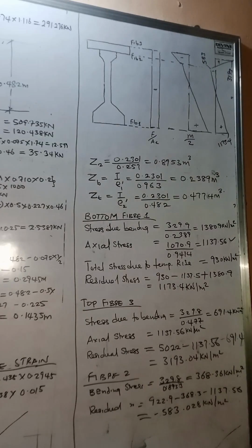All right, so this brings us to the end of this lecture. We can work out the reverse temperature for this problem to obtain the residual stress. So these are the stresses at the beam. Once the stresses are known, if you are designing this beam as pre-stressed concrete, you have to take cognizance of this stress. If you are designing it as reinforced concrete, of course, you can still do a check for stress, which depends on the type of concrete strength you are using. And you must ensure that all stresses comply with the limits set by the code.